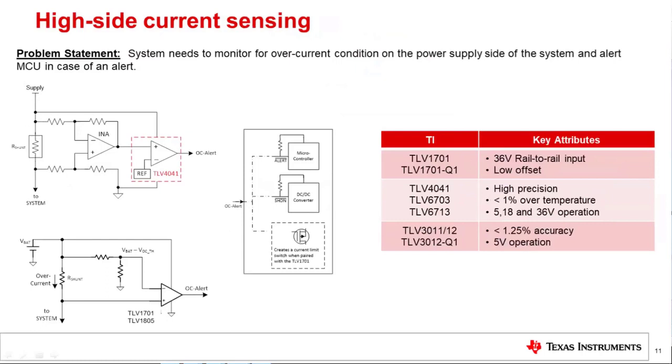If I'm monitoring a battery voltage, it's not fluctuating at a very fast rate. So depending on the voltage I need, I can typically optimize my system for a slower response. And what that buys me in turn as my customer is much lower power consumption, right? So it becomes like a nanopower or micropower autonomous voltage monitor. That's one common usage case.